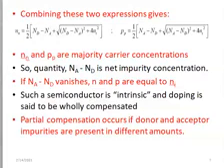And how do we prove this? Go back to this expression. Whenever, under these square roots, Nd minus Na becomes 0, and here also Nd minus Na becomes 0, you will be left with the square root of 4Ni squared, and that will give you 2Ni, and this half will cancel that, therefore Nn is equal to Ni. The same thing here: when Na minus Nd is equal to 0, we will be left with the square root of 4Ni squared, and if you take the square root, it will give you 2Ni. Multiplied by this half outside the bracket, that will give us Pp equal to Ni.